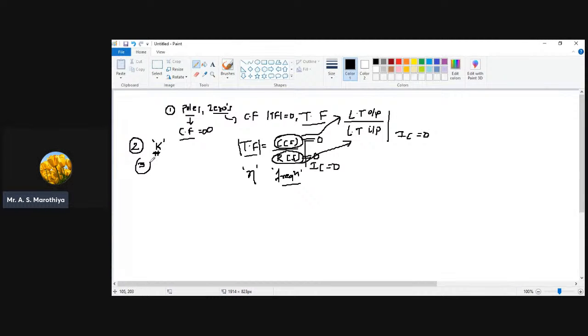Then the third thing is we are in a position to identify the order of the system as well as the type of the system. In the coming sessions, we are going to discuss in detail the exact meaning of order and type. But for the time being, let us consider that if we know the transfer function of a system, we are in a position to identify the order and the type of the system. That is important. Then if we know the transfer function of a system, we are in a position to identify whether the system is stable or not.